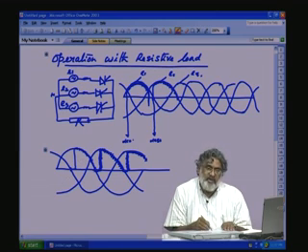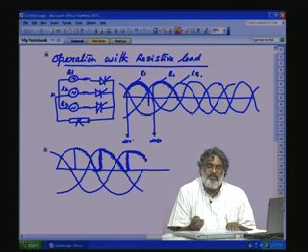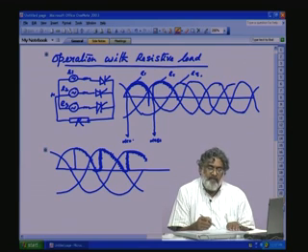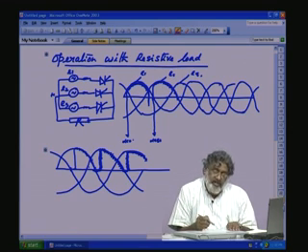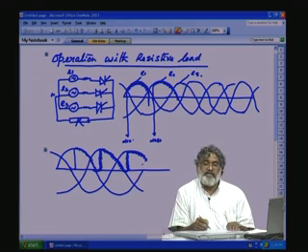At alpha equal to 180 degree, the output ripple coming across the load is 0. That means output voltage is equal to 0. So, this way also with resistive load, we can have 0 to positive voltage variation possible.